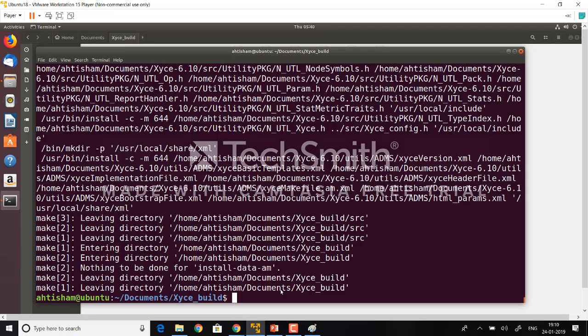If you see our model, this ASM, all these surface potential equations, the surface potential calculations, they've been done as macros, not as functions. Maybe 50 lines of code, surface potential equations. You won't do them in analog functions, or your code will be extremely slow. You do them as macros. And for macros, you have to escape the new lines so that you make multiple lines. I'll just show you.